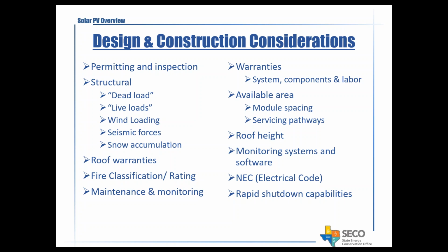Very important is the fire classification and rating. I think the new codes now require that the PV systems have the same fire rating classification that the roof system is going to have. So that's something to just keep in mind.